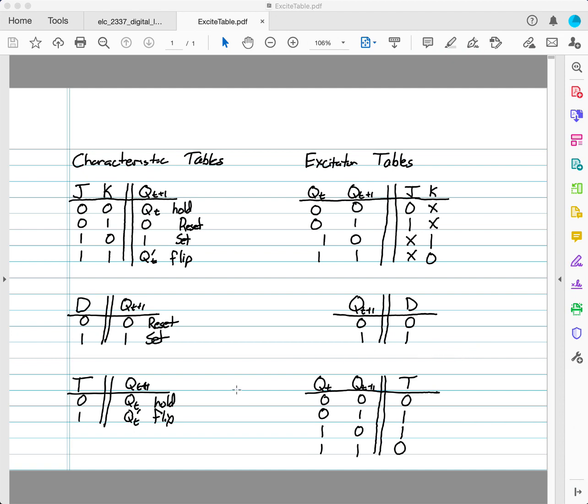The last one I'm going to do is a T flip-flop. You'll notice I'm not doing the SR flip-flops because SR flip-flops essentially are just the upper part of a JK. It just doesn't have the flip option, but it does have the option to go bad on you. So we don't like that. We want safety. This is basic digital logic design. If you go to advanced digital logic design, we will like SR flip-flops again because we want speed. But then we have to be careful. Right now we're all about safety for the first course. So, safety wins and away we're gonna go.